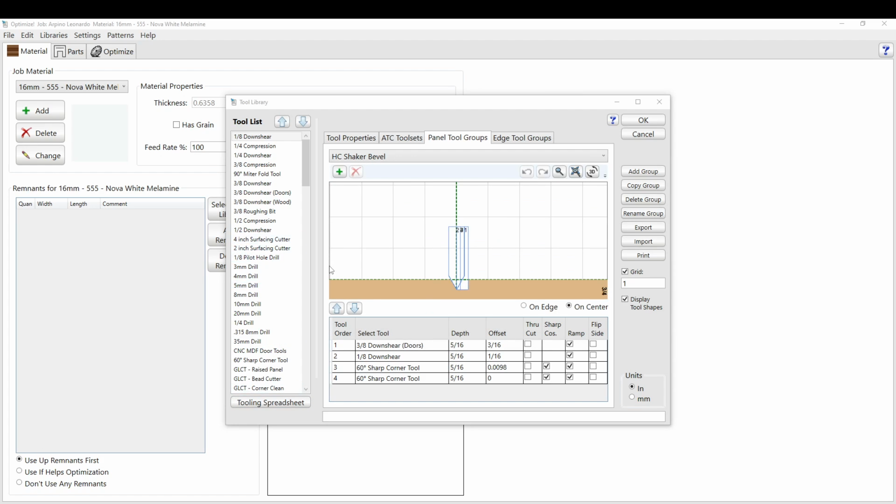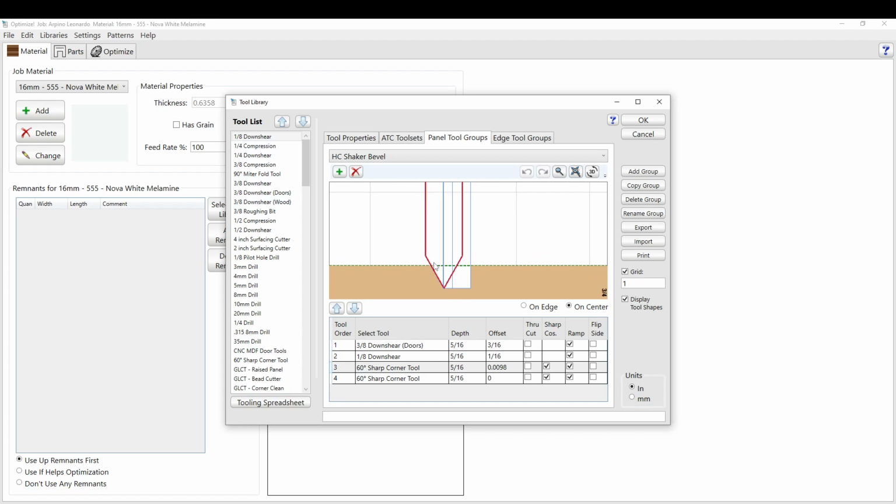Okay, so I think I messed that up when I added the big bit in there, so my offsets were a little screwed up. So this is how you really want it to be set up. You have your bevel bit. This is my 60-degree vortex bit, and you want it right centered, the same depth as the rest of all your tool passes. I do that third in the tool order, and then I do another one a little bit deeper. Basically 10 thou deeper, higher, so that's higher, and then this one's just a little bit deeper.